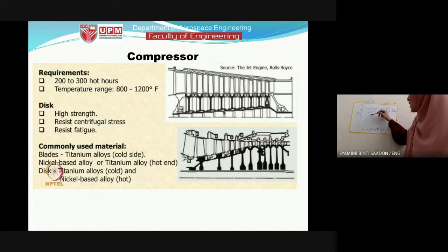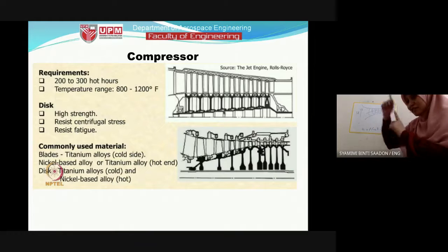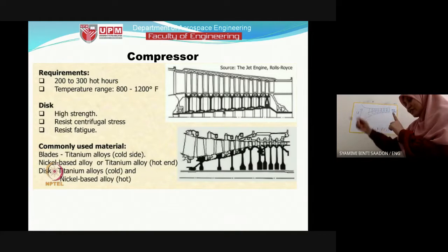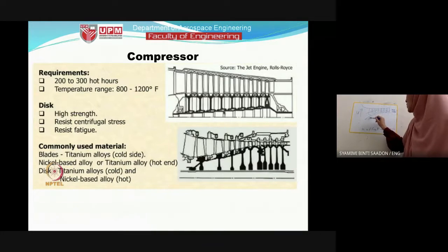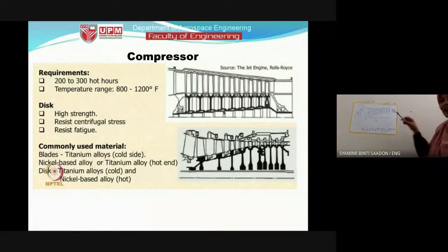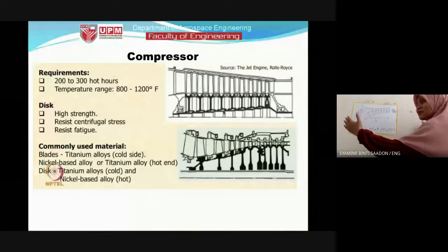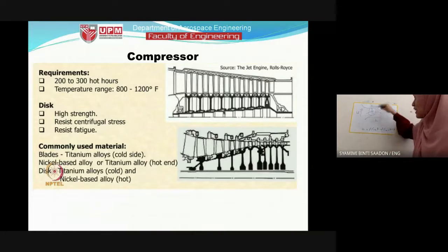So 2 pi r, imagine for one blade, and we multiply it with h, the total height of the axial stage. So 2 pi r is only one, and then we multiply for the whole stage height, h. So that is the mass flow rate for the axial compressor: rho 1 CA1 2 pi r h.